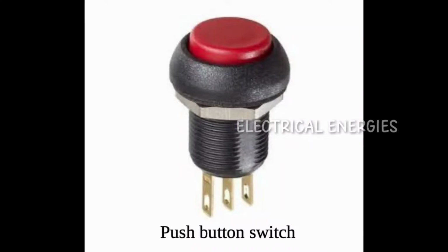Number 2. Push-button switch. Push-button switches are two-position and activated with a button, which is pressed and released. Most push-button switches have a spring mechanism built in them that returns the button to the unpressed, out position, at least for momentary operation. There are push-button switches that latch on or off, in alternate fashion, for every push. Others stay in the in position until the button gets pulled back.